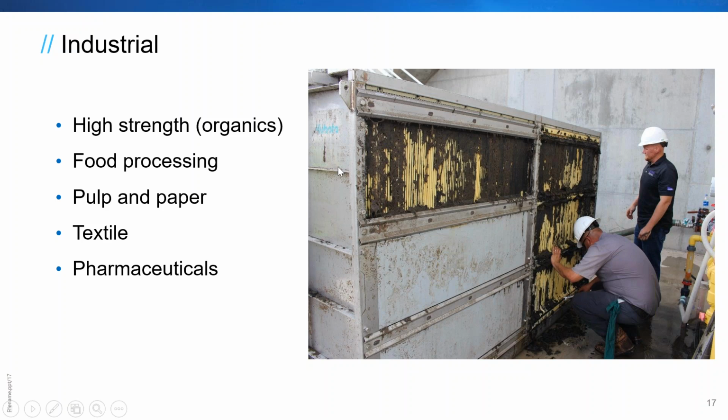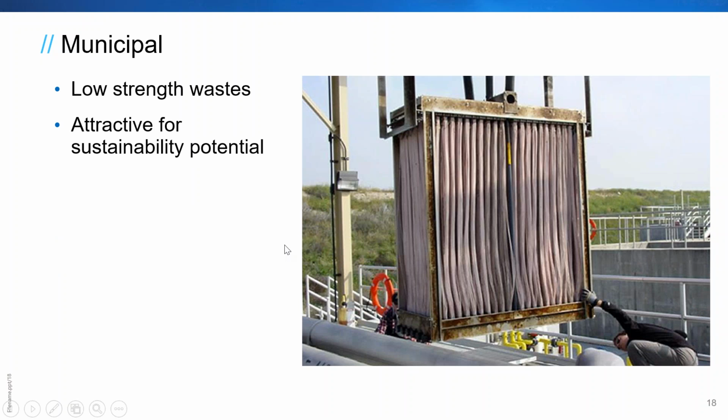And of course, that leads into kind of a municipal concept, is where you can see a challenge is municipal wastewater, especially relative to industrial wastewater that could be a BOD of 5,000 or 10,000. We're lucky to see 250 or 350 on a municipal side, which can create a challenge to make this process viable. But it is, of course, one of the challenges that we all in the industry are willing to take and try out, especially because they're attractive for sustainability potential, right?